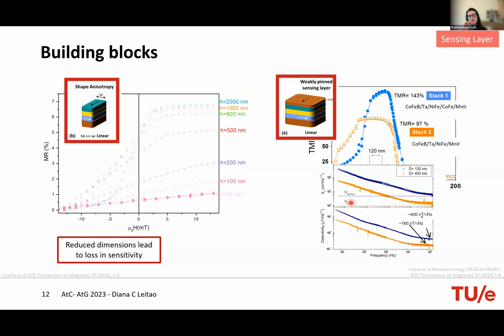And notice also here that we focused a lot on the low frequency part, because we were targeting bio applications, so mapping slow time dependent applications. In this case, the 1/f noise is dominant, and of course the magnetic component of the 1/f noise will be even higher. So long story short, local fluctuations of the magnetization at the free layer are quite significant.